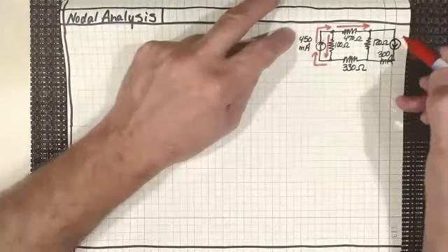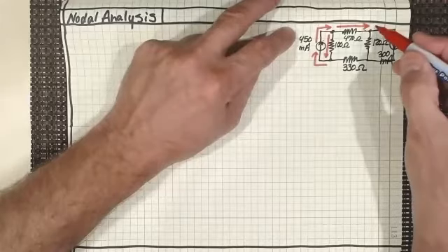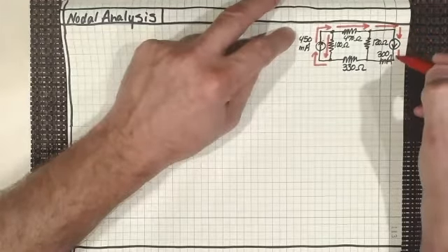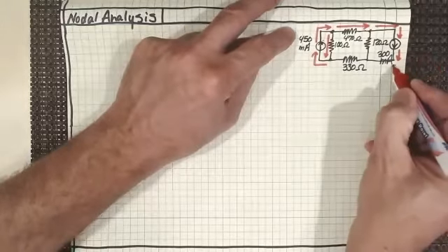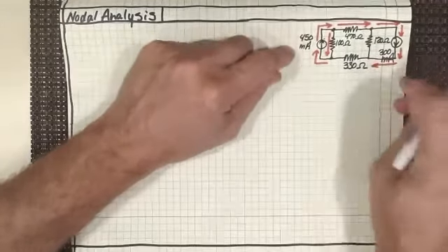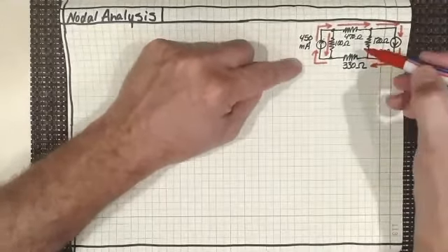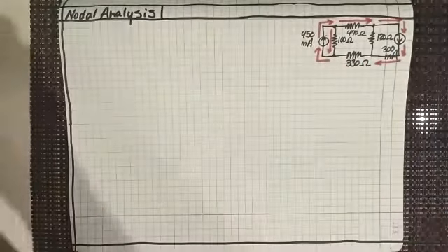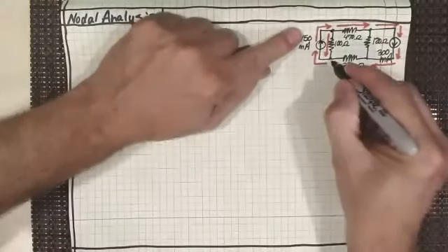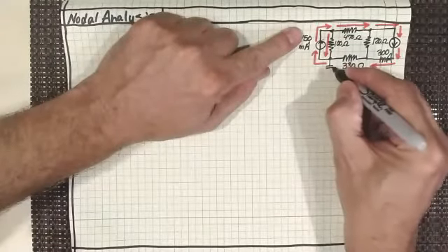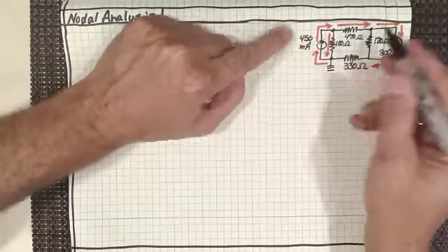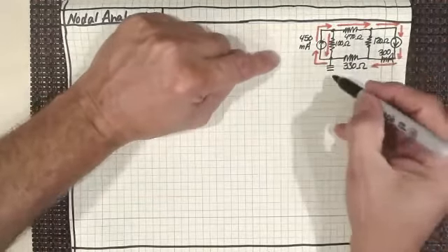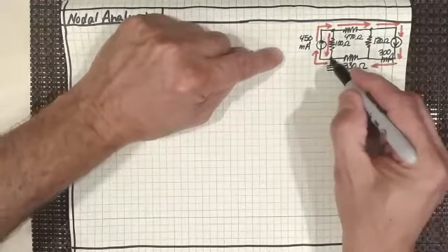We know another thing. We know that this is definitely flowing in this direction, and we know what its value is. We know its value is 300 milliamps. Oh, I forgot to put our ground in. Excuse me. Let me ground this right here. Usually, you know, the base of a power supply, but then how would you know which of the two current sources we are going to ground? So I'm going to say that this is 0 right here.